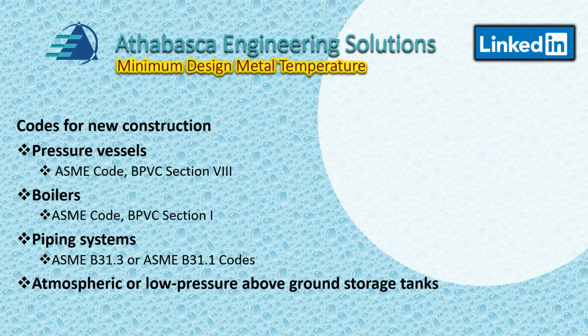We have atmospheric and low pressure storage tanks, and all these specs have specific requirements for impact testing. B31.4 we'll get to later. It doesn't provide anything as specific as B31.3 or B31.1. But also going back to the tanks, API 620 and 650 have very specific requirements, especially 620, because they're all into the cryogenic type services.